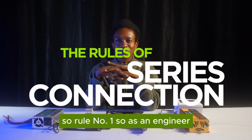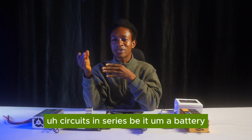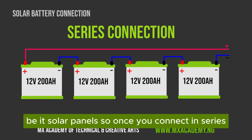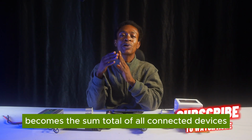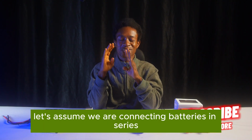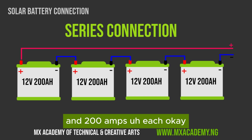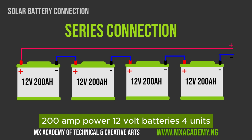Rule number 1. As an engineer, you should have it in mind that when you connect in series, be it batteries, an inverter system, or solar panels, the voltage becomes the sum total of all connected devices. Let me give an instance. Let's assume we are connecting batteries in series. In this instance, we are going to use 4 batteries of 12 volts each and 200 amp hours each.